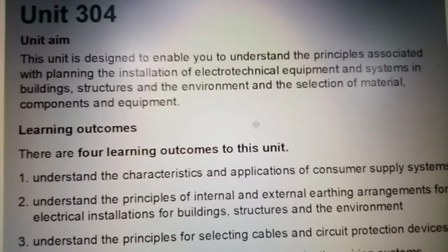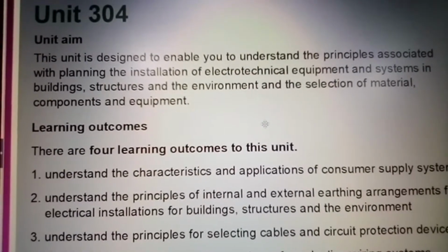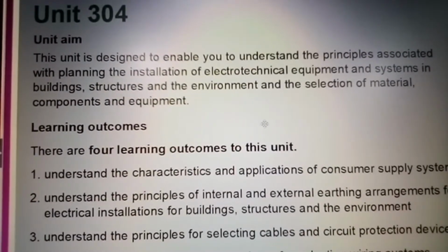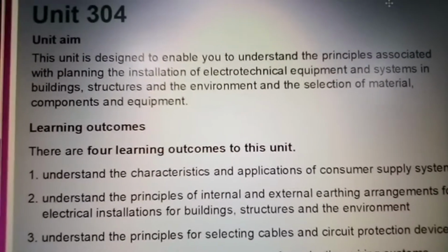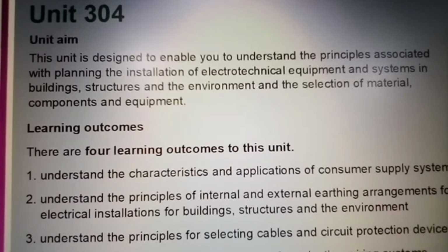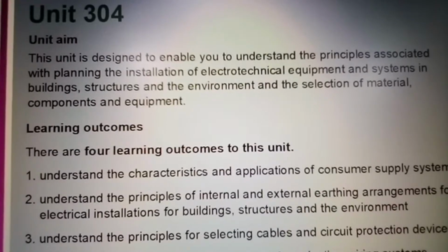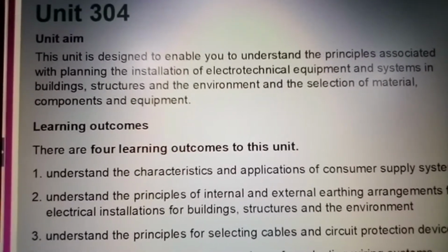Now, that is still up for debate from what I can understand, but check the IET regs first before you do anything, because that is probably due to change or have amendments made to it. But from my experience at this point in time, I would apply a TT system plus the supply earth, and that's what I would go with at this point in time. But check the IET regs for the correct procedure. Look and read the information that comes with the unit.